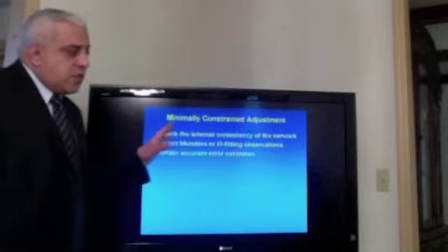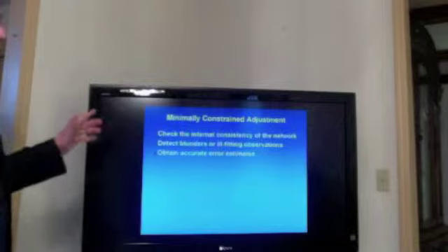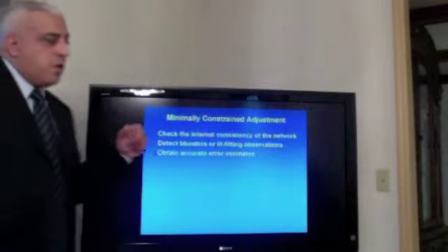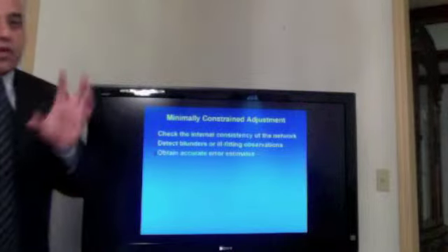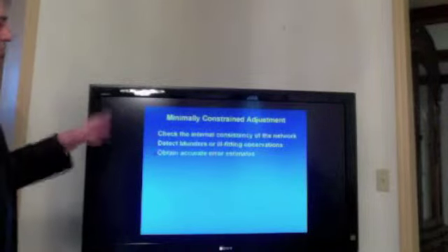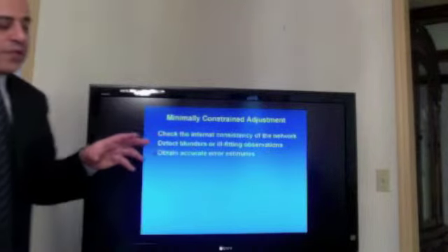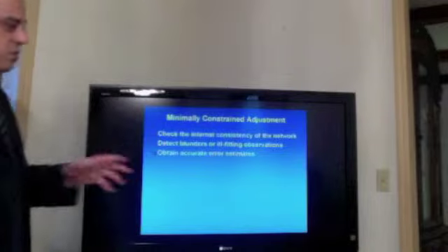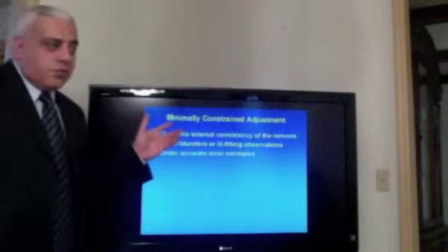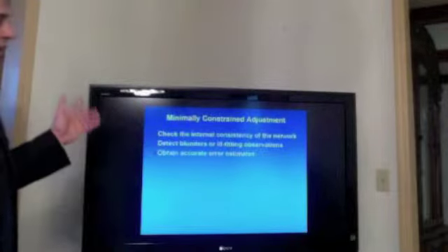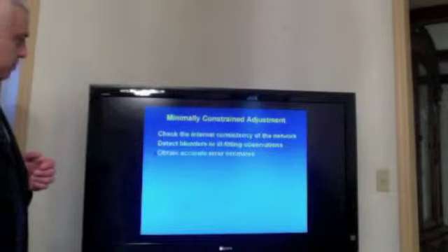The error estimates here are very important because before we enter this process, we hypothesize that we have a certain weight for the measurements, but during the observation itself, we do have different conditions. So we need to scale our errors to be able to get a successful statistical evaluation for the network.